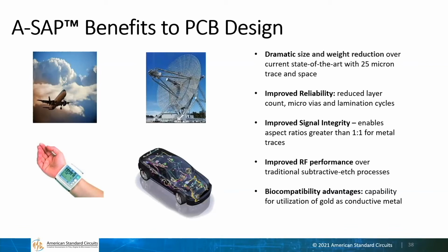So you'll have a better controlled impedance line. There'll be less variability in that impedance over different boards and different panels and over the lifetime of the product. So that gives you back some of your budget for your signal integrity and your signal path by having better control of those controlled impedance lines. You could also do other things like broadside coupling due to very narrow spaces and high aspect ratios. You can get true differential lines and a bunch of other things, which we'll mention a little bit later as well.